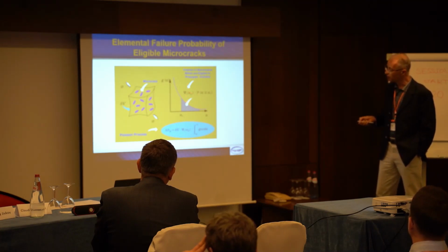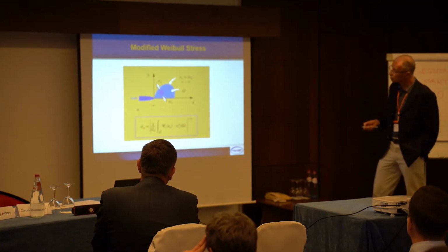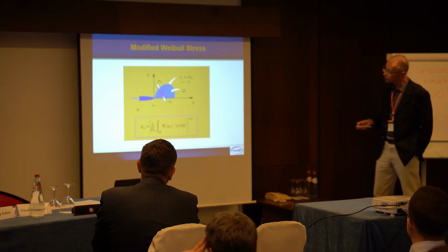Okay? So we came up with a modified Weibull stress, which incorporates the fraction of eligible microcracks which affect the cleavage process.